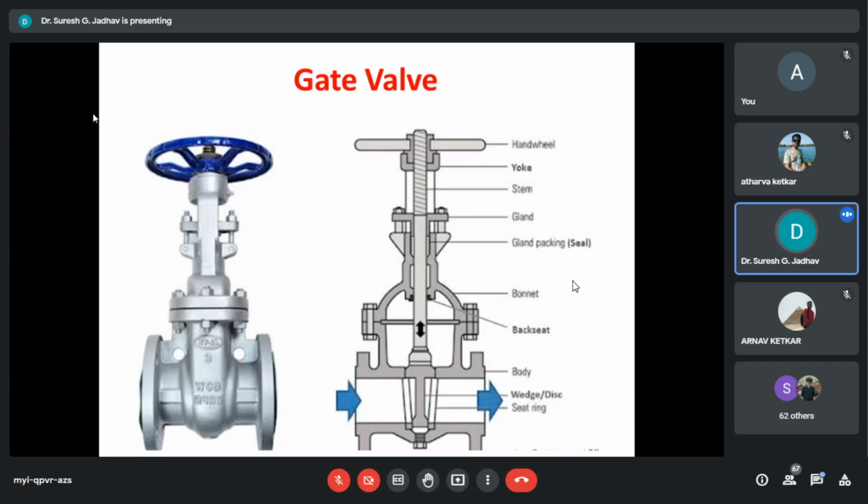This design is used mostly in low pressure valves. Normally, the gland follower will be of superior material than the gland flange. Gland flanges are made of carbon steel only. The gland flanges are bolted to the bonnet with gland eye bolts in low pressure valves.